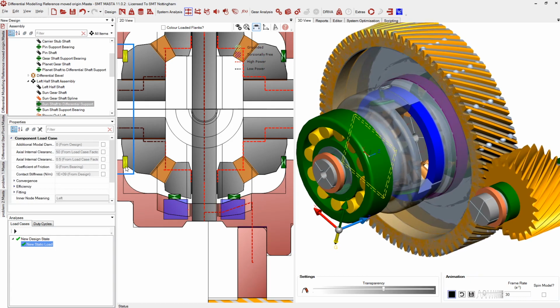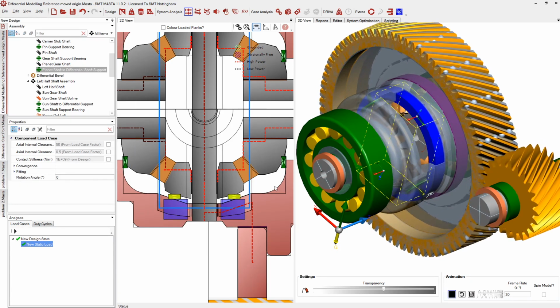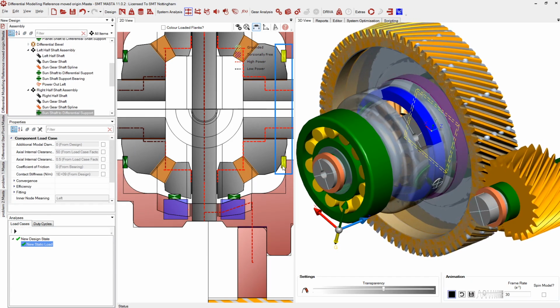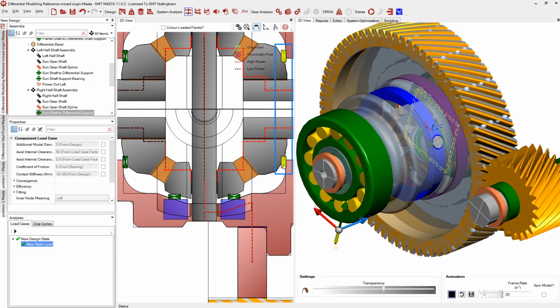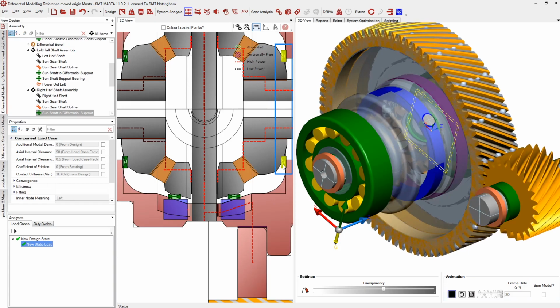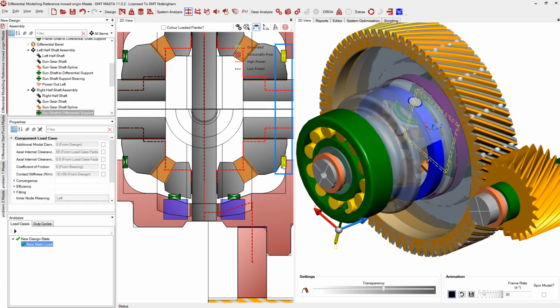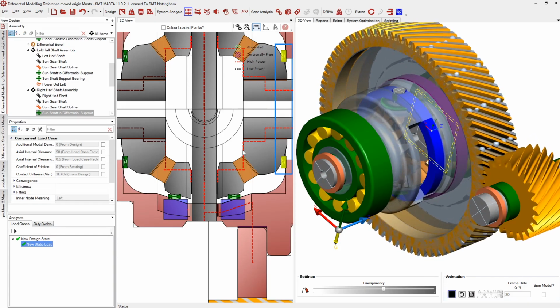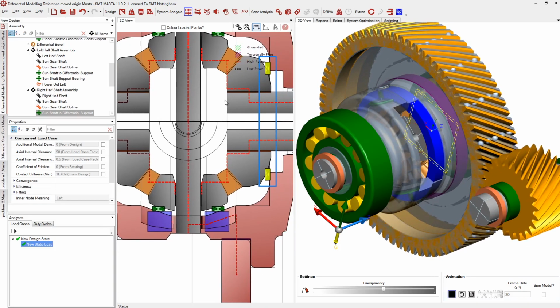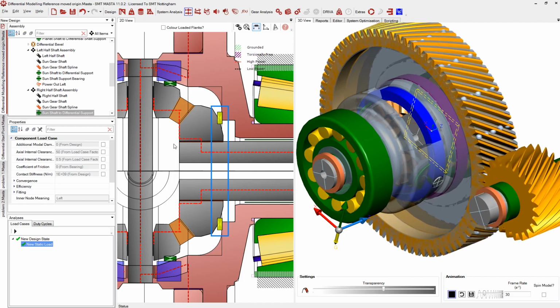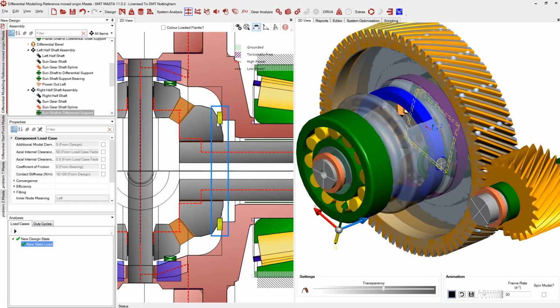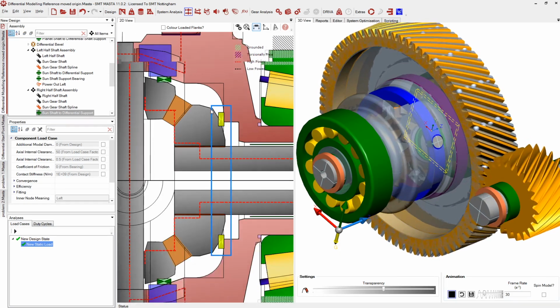Now starting with the clearance bearings we have here, these are, as the name suggests, just to model any clearances in the model, and they allow us to fully constrain the system as it would be in reality. For someone who's not very well versed in creating MASTA models, it can sometimes be a little confusing as to why these are necessary.